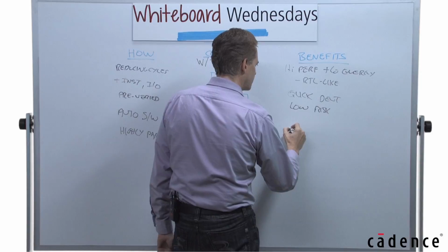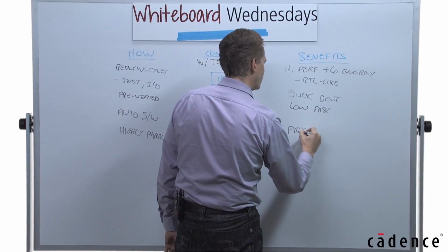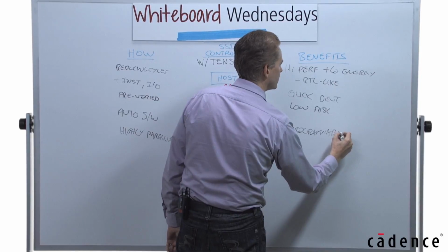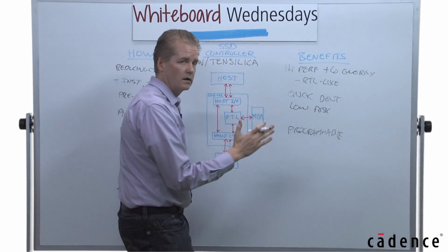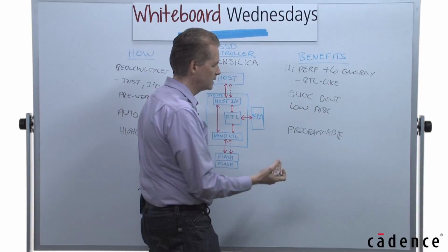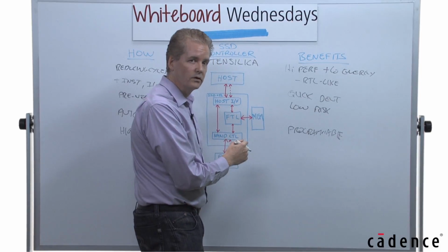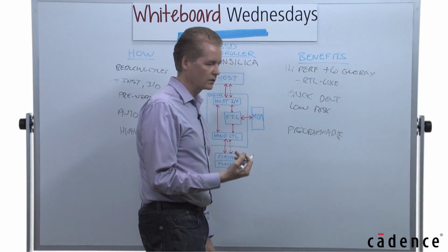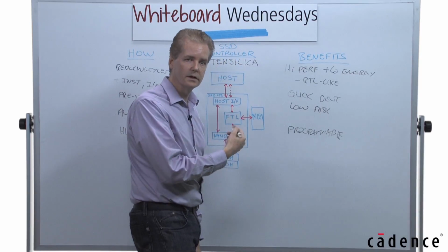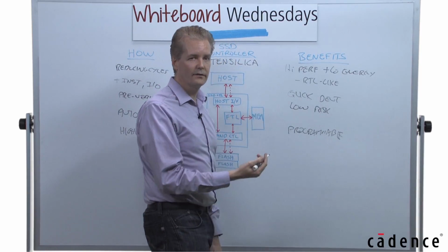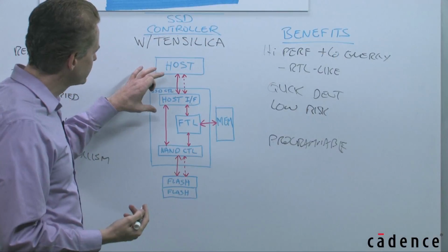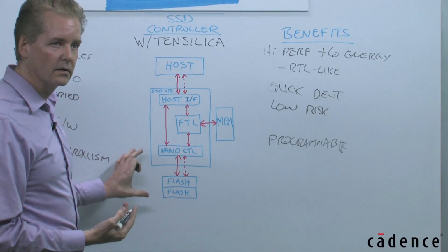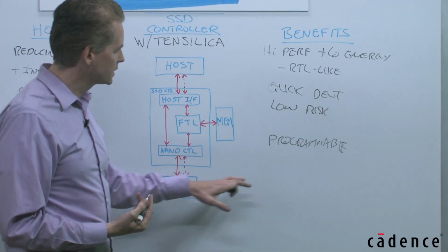And then because of the generation of all the software automatically for you, you retain programmability. Whereas with an RTL offload, you're limited in flexibility. Now you retain the programmability that you originally had, because all we've done is added instructions and I/O to the processor, which means you can make adjustments right up to tape out and even after tape out. Because sometimes the specifications on the host interface and the flash interface can change at any time. So it gives you much more flexibility.